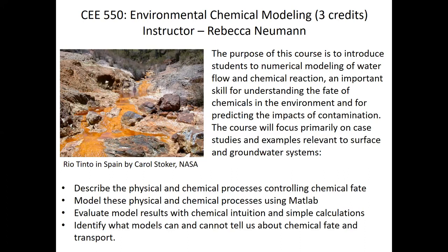One of the interesting things that I've learned from her research is that Bangladesh has some of the biggest problems in the world with arsenic in the groundwater, but there's actually no more arsenic in the subsurface matrix of Bangladesh than there is in other places. It's just that the conditions in Bangladesh are very favorable for that arsenic to be in its reduced and mobile form. So she's doing some fascinating research and has some very interesting course opportunities.